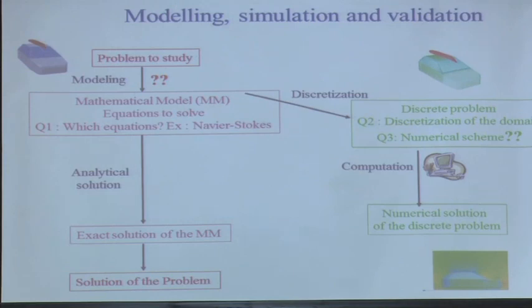At some point you will make your simulations, choose your algorithm, define your domain, but if you just run the simulation and you don't know what you expect, it will be very difficult to know if it is accurate or not. If you compare straight to an experiment, you will see, of course, discrepancies, but you will never know if it's because the model is not correct, your computation is not correct, or because the experiment contains some errors. So it's very important to get some analytic solutions, so you can compare your discretized solution to something which is, of course, correct.